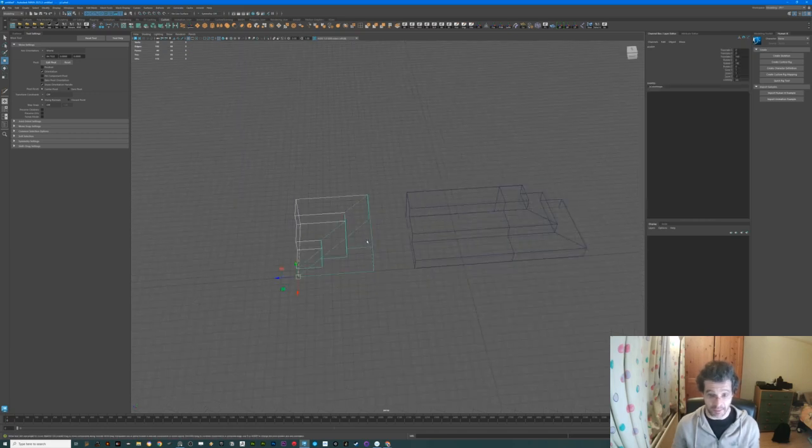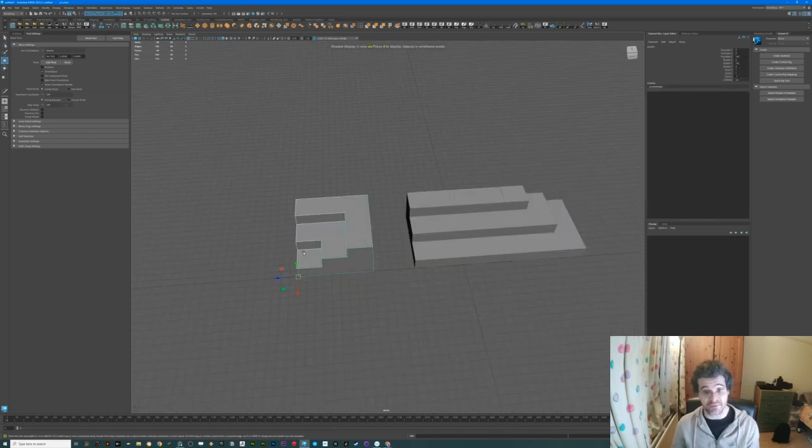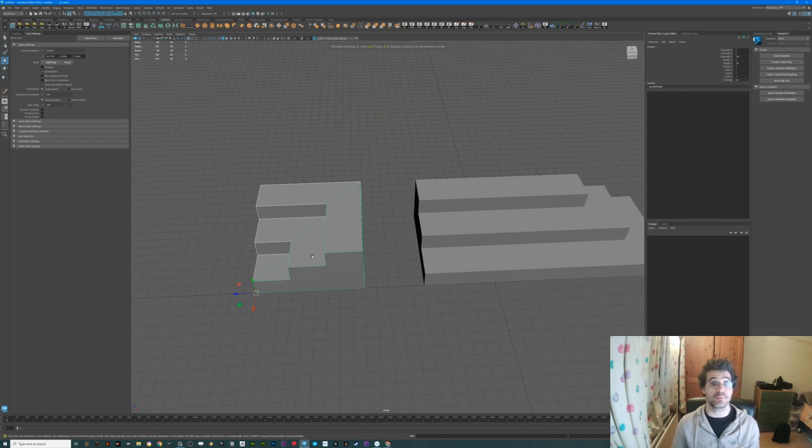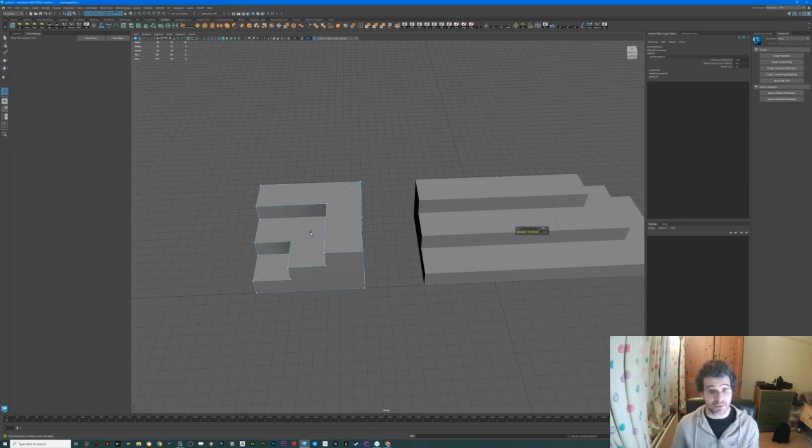Okay, so I'm back here. I'm going to press 5 again. I'm going to Shift right mouse click, press combine, right mouse click, vertex, select all of them, press Ctrl F, merge, and now Shift right mouse click, vertex normals.